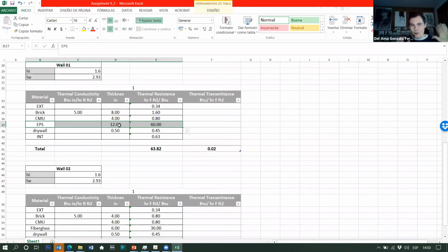Just by remembering these two figures, we are safe. Even if we don't have an Excel file or a calculator, if I design a wall with 10-inch thermal insulation, it's more than enough for New Hampshire. If I'm in Alaska, probably it will be 20 inches.